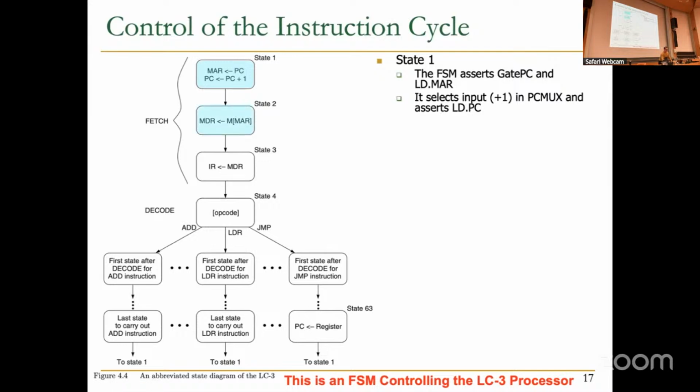The next state is memory access state. Basically, you wait until the memory returns the data in the MDR. So you need to make sure that the load MDR signal is asserted. But this is just instructive because it doesn't have an arrow over here that should be going. This is a conditional. It's a state where you stay conditionally. If the memory is not ready, you keep staying in the state until the memory becomes ready. Okay? You will see the full picture in the next slide.